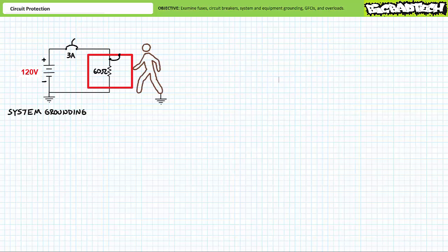Any unfortunate person bridging the accidentally electrified frame and ground completes a conductive path. Let's say this unfortunate person draws 30 milliamperes of current, an extremely dangerous, painful, and damaging amount. The source supplies 2 amps to the device and 30 milliamperes to the operator for a total of 2.03 amps. Despite this dangerous occurrence, the rated current of the circuit breaker servicing this machine is not exceeded, and the circuit breaker will not trip despite the obvious safety hazard.